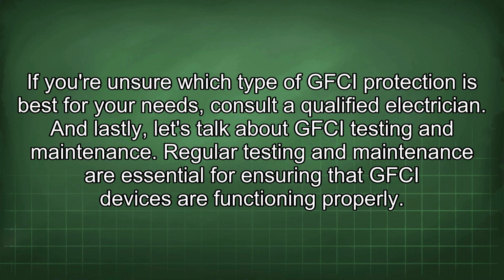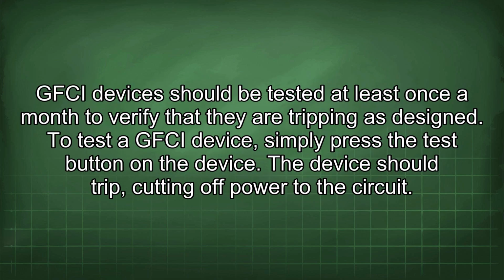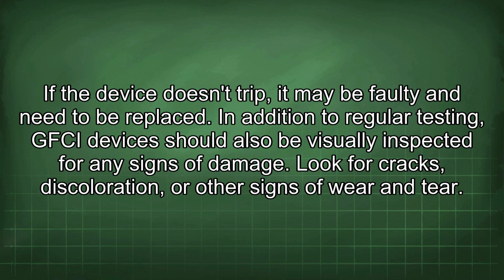And lastly, let's talk about GFCI testing and maintenance. Regular testing and maintenance are essential for ensuring that GFCI devices are functioning properly. GFCI devices should be tested at least once a month to verify that they are tripping as designed. To test a GFCI device, simply press the test button on the device. The device should trip, cutting off power to the circuit. If the device doesn't trip, it may be faulty and need to be replaced.